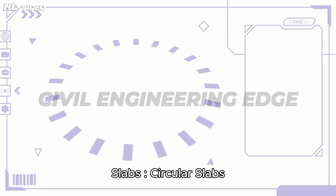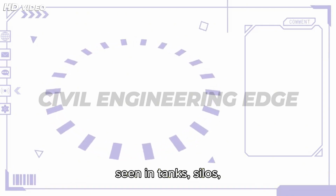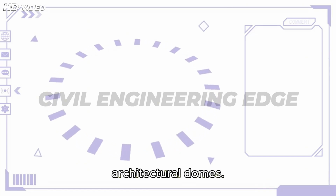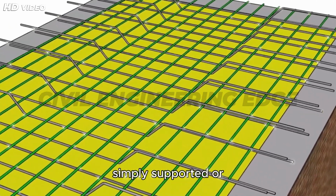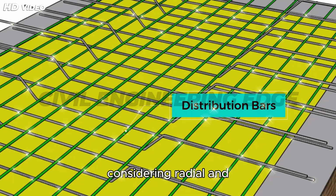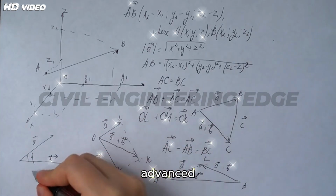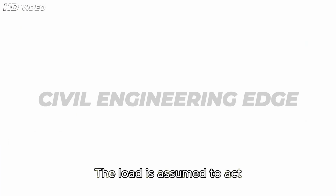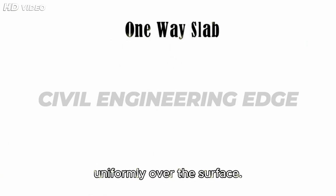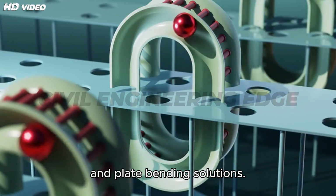Design of circular slabs. Circular slabs are slabs with a circular plan, often seen in tanks, silos, fountains, and architectural domes. These slabs may be simply supported or fixed along the edges and are designed considering radial and circumferential bending. As per IS 456:2000 and advanced structural theory, the load is assumed to act uniformly over the surface. Bending moments develop along radial (Mr) and tangential (Mt) directions. The design is based on elastic theory and plate bending solutions.